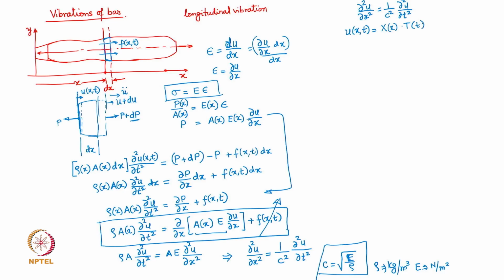Okay, and I can get the same expressions. Now this equation is quite the same as the expression for the string case, so you will find that we do not have to repeat the whole process. We can definitely show that this is going to be a cos(ωx/c) + b sin(ωx/c), and then the time function is going to be c cos ωn t + d sin ωn t. That's the second part of the total solution.